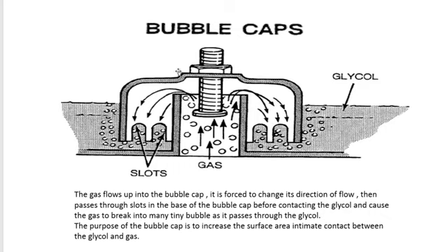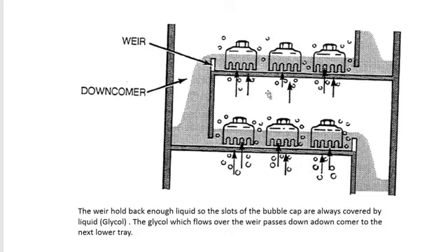What is the purpose of this bubble cap? The purpose of this bubble cap is to increase the surface area and intimate contact between the glycol and gas. Okay.